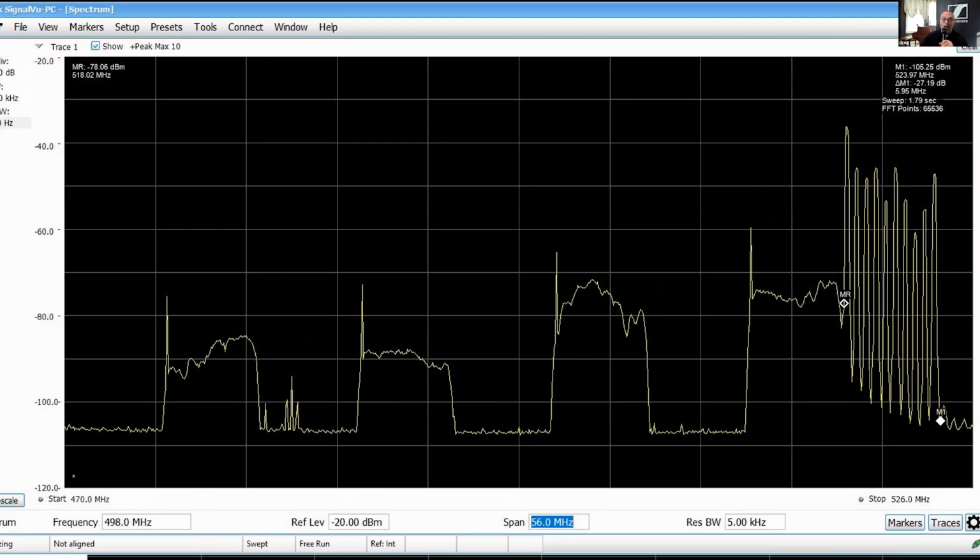You also see there on the bottom left, there is some other interference that's happening. That might be a life safety system. That could be something else that was near the scanner or in the area. But even though this is a crowded spectrum with a lot of other stuff going on, Evolution Wireless Digital can still get over 50 channels in this space. You could get 10 in between, the gap to the left of each of those channels that we already have. You can get probably another 10 down at the bottom, maybe 7 or 8 channels where that interference is, and even a few more above since we have a little bit more spectrum to work with.